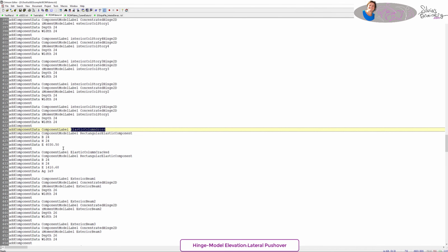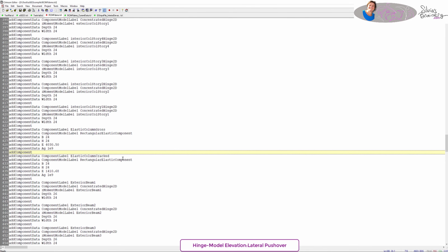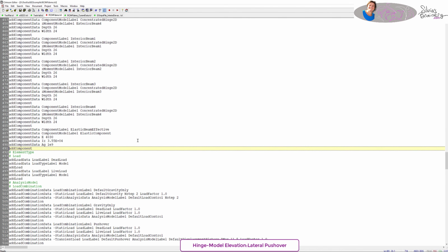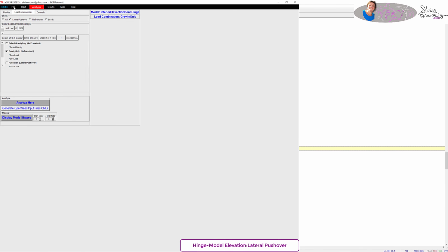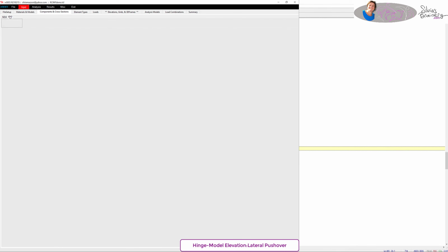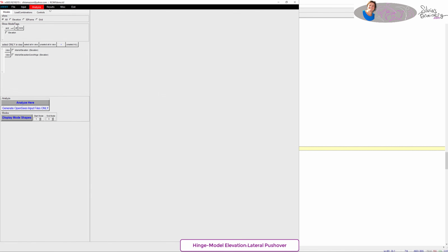I did something wrong because, oh, I realized I needed to update the stiffness. So looking at periods and mode shapes is really helpful in debugging your model. So I wanted to make sure that that's there as well. You run your pushover analysis. I'm trying to just have a look at things. Okay, yeah, it looks good.